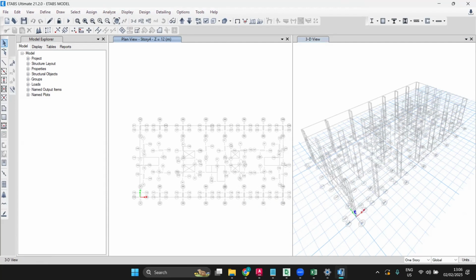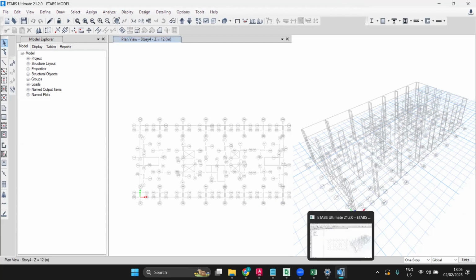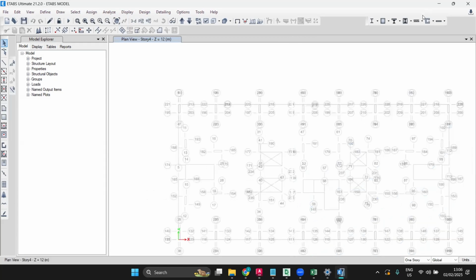Keep it in story mode. Why keep it in story mode? Because you are going to bring the model from story mode. If you keep it in the fourth or third, again you need to bring it back. The modeling you're going to do is from down, so it's a double and triple job for you.